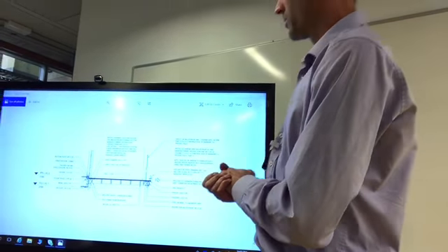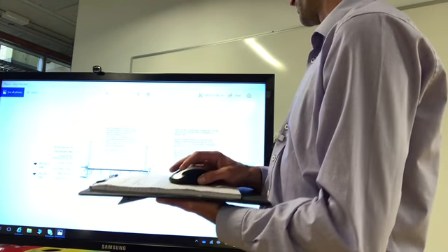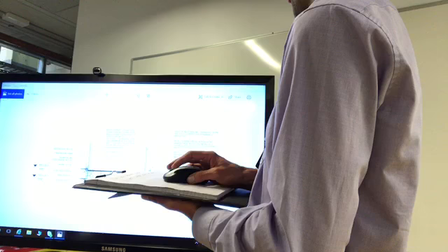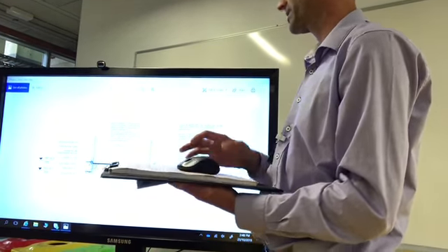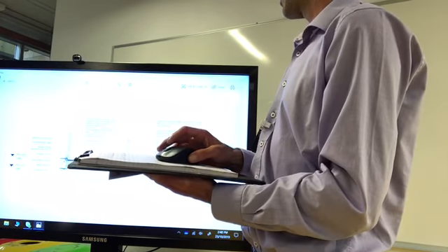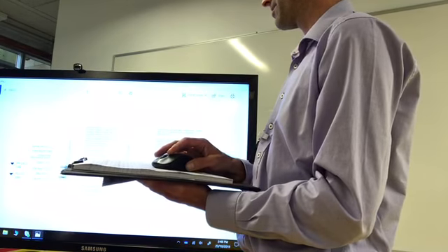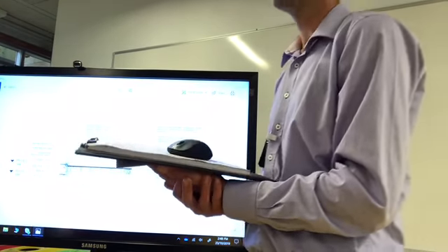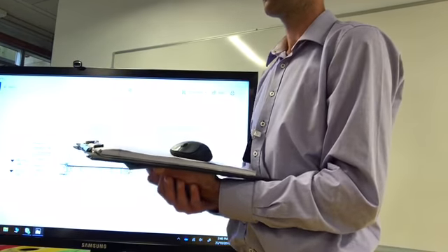So what similarities will there be? Whether it's framed or a continuation of that concrete slab, you're going to have to provide a set down. This set down is so balcony finish floor level minimum 50 millimeters and maximum below internal finished floor level, and they've set it at 96. So you're going to have a minimum of 50 millimeter set down from your floor to your balcony, and if you're going to be tiling your balcony, you'll have to give it that extra 10 millimeters for that.